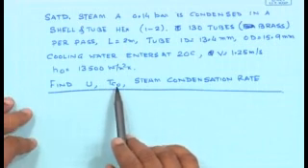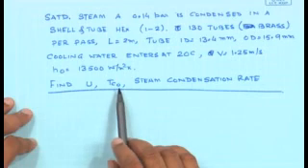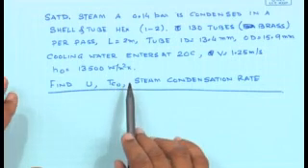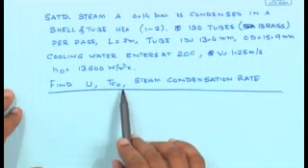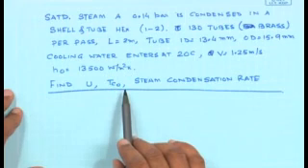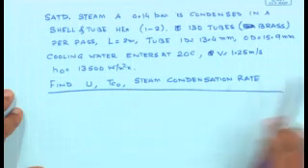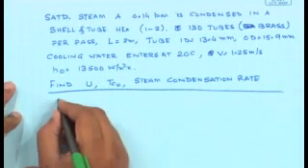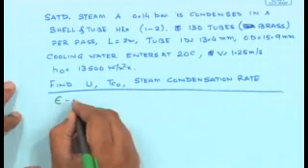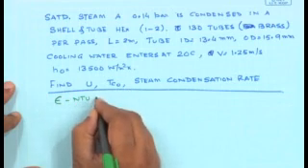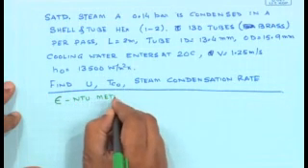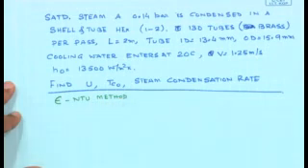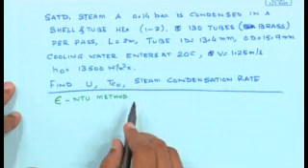On the other hand, this is a case where the steam is condensing and there is no change in temperature in that phase. So CR is 0 and therefore a straightforward relation between epsilon and NTU may be available. So this is a perfect example, a prime example for the use of the epsilon NTU method. We would do that, but in order to do this, we need to know some of the properties.